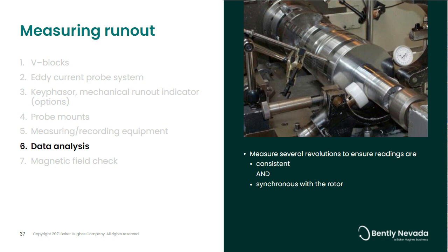Are there any pieces that are moving? Are your Teflon pads shifting? Is the lathe perfectly centered? Are your probes mounted very securely? Are they shifting? Is the magnet for the post and rod holder mounted on something solid, or is that something shifting as the machine rotates? All of the variables need to be as consistent as possible so that the readings you get are as reliable as possible.